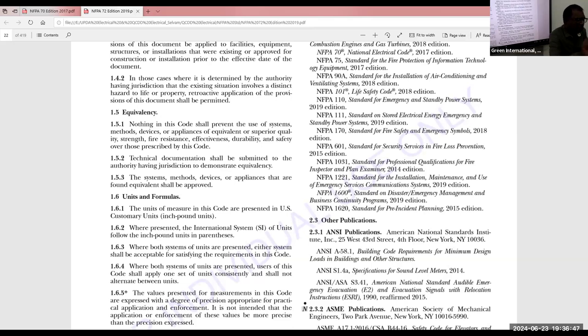Diesel generator. Usually they mention 1000 kVA DG. Again, 1000 kVA DG is the term we usually use on site, but in the BOQ there are more than 5 to 6 different lines. They mention 1500 kVA standby generator or prime generator. Depending on the project, they make different things. But here, for NFPA 110, it refers to the standby generator. But for the prime generator, we need to refer to NFPA 70.